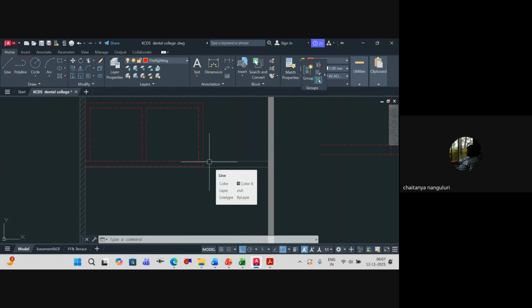Yes, you were telling something. Now, generally, what we do here also is that we make a clear partition. Technically, you have to make it, but in many tech parks or wherever you see, that philosophy is not followed. Technically, yes, you should have a partition with separate fire rated walls, and it should have a fire door. Understood?